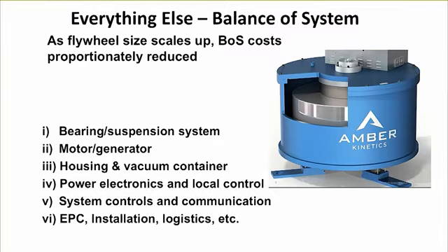In terms of bearings, there are mechanical ball bearings, relatively conventional but still special, inside the box here that hold the rotor at all times. The bearing life is a function of how much load is on the bearing and how fast it is spinning. And by having a magnet that takes up basically 100% of the weight of the rotor, the stress on the bearings is very low. And so, yeah, the bearings can still fail.